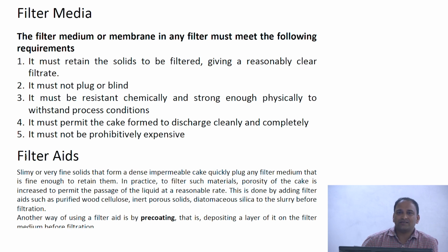What people do is they add some additives. These additives are inert. They don't do any other job. They don't chemically interact with the liquid, nor the solid. They're inert particles, and the moment you add them, they will try to maintain a typical porosity throughout the filtration process. It will prevent the formation of these dense, impermeable cakes. Therefore, the filtration can continue for a longer period of time.